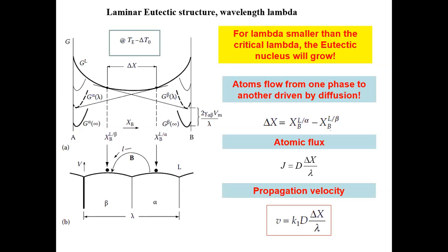That makes sense to you? So basically, the rate of flux for the B atom is the same as the rate of flux for the A atom. This justifies why it's sufficient for us to look at only one particular species, because the other works in the exact same way. Because of the symmetry we induced, which simplifies the problem, A atom diffusion occurs at the same rate. So you only need to construct the one coefficient, which is proportional to delta x. We do not say delta xB or delta xA because they're symmetric, and this delta x is the same. There's only one flux and one numerical gradient. Does that make sense to you?